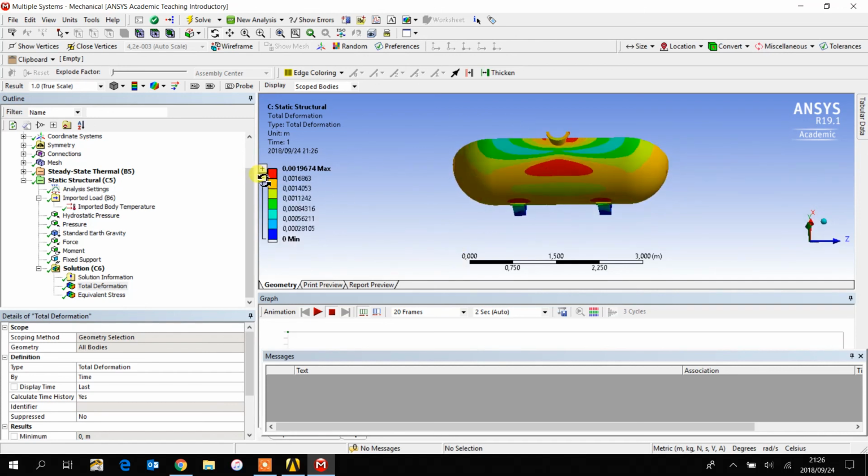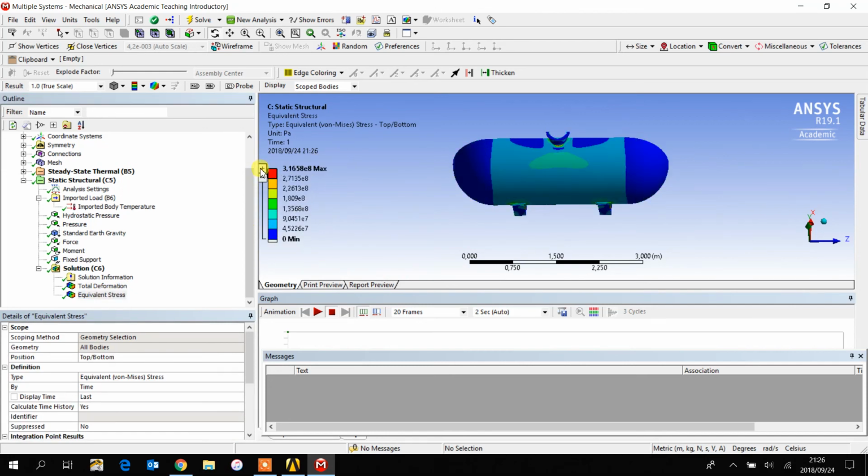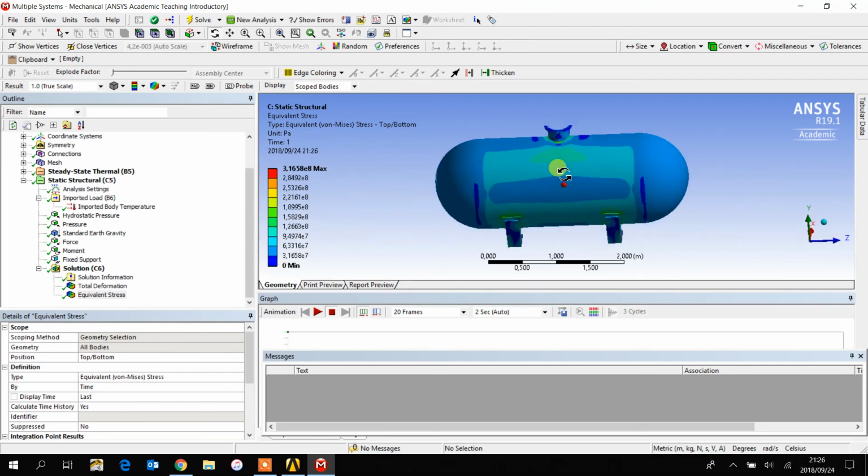The only thing that I'm confused about when reaching the end is the deformation, and also let's go stress, and the stress appeared to be completely symmetrical about the neck of the pressure vessel. And if you think about it, there should be more stress on the one side than the other because of the force and the moments acting in the same direction. So if you look in his document, it shows that there's more forces in the one than the other.